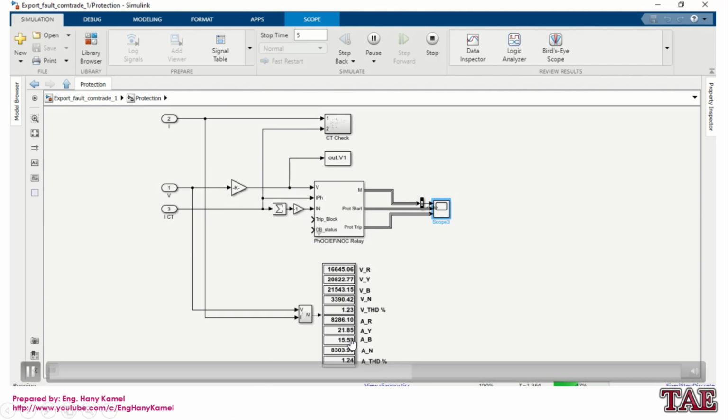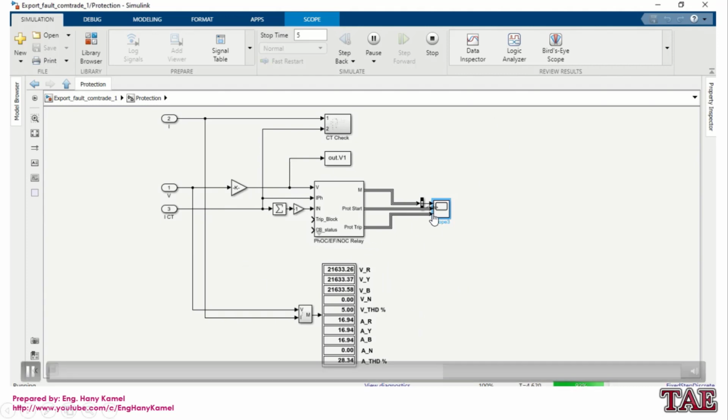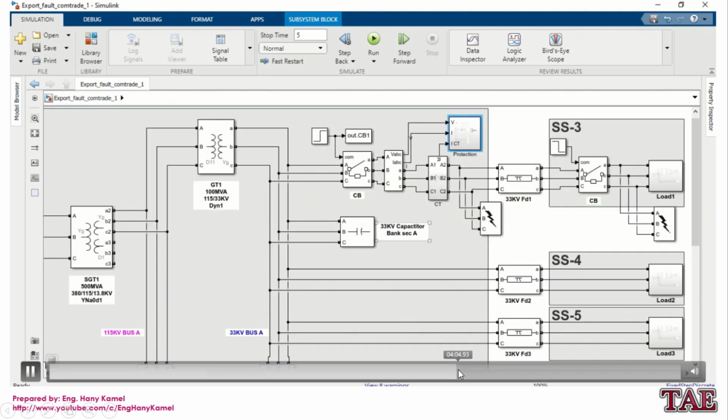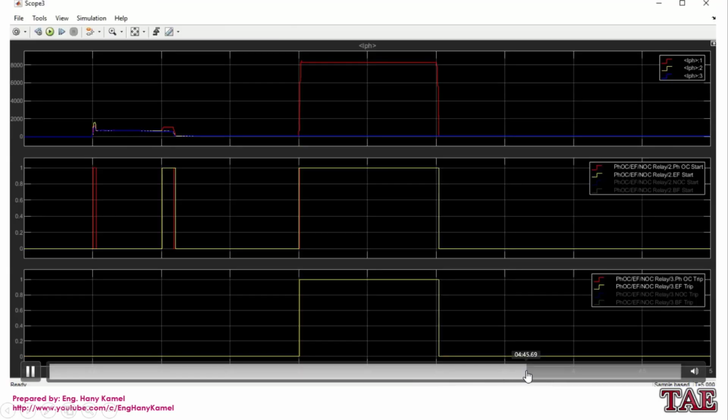It is now a higher fault. As you can see, it will stay for 1 second, and after 1 second it's cleared. As we said, I already isolated the trip circuit, and I kept only the fault for 1 second. So now we will check the disturbance record.